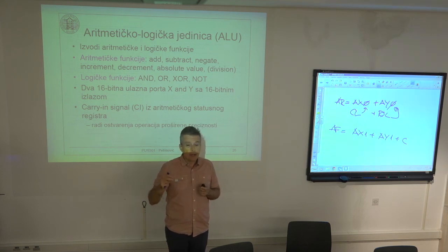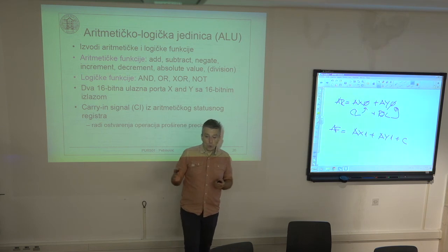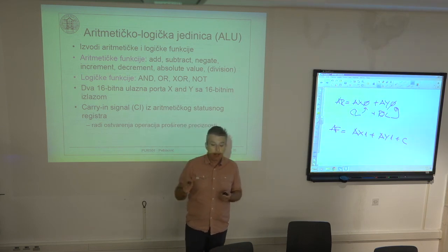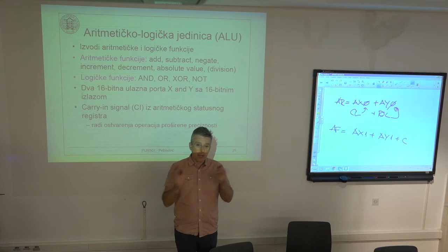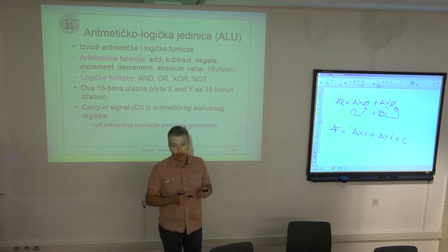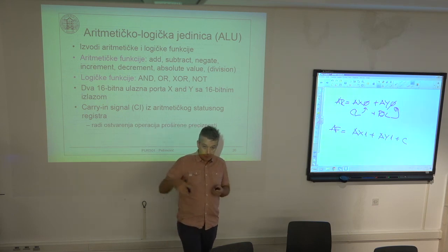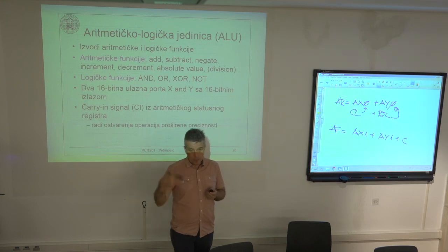Exactly as many times as how many quotient bits I want to compute. If I want to compute 16 quotient bits, I have to repeat this primitive instruction 15 times and one additional instruction one time. So first, one instruction computes the sign bit of the quotient, and then I have to compute 15 fractional bits by repeating this division instruction 15 times.